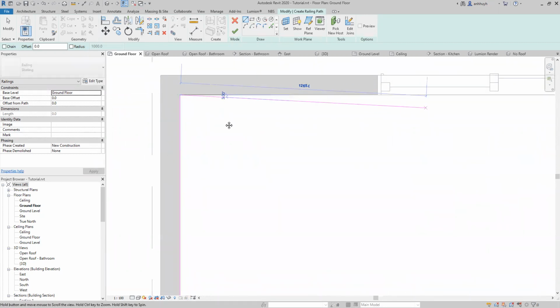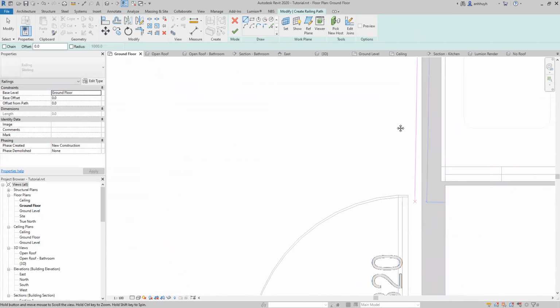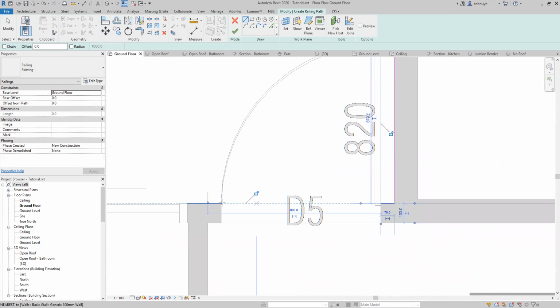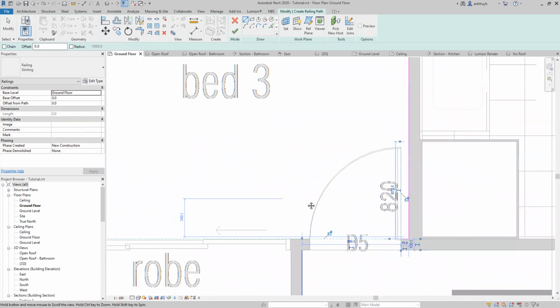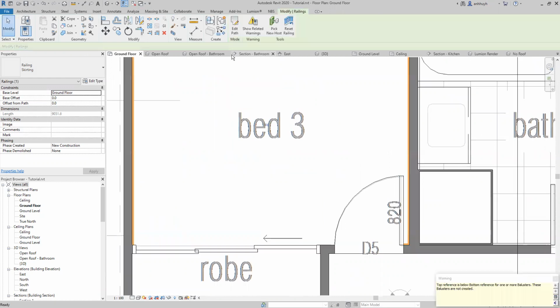And we're going to make another line for this wall and another line for this wall. And we're going to stop at the door here. Okay, we don't want the skirting to go through the door. So that's it. That's the first part of the railing for this room. So complete. And it gives you a warning that balusters couldn't be made. That's fine. We don't want balusters for the skirting anyway. So you can ignore that warning.